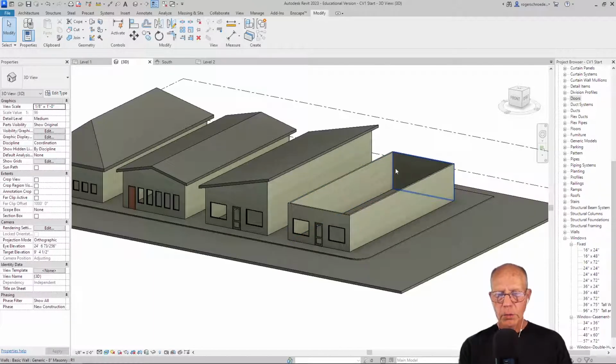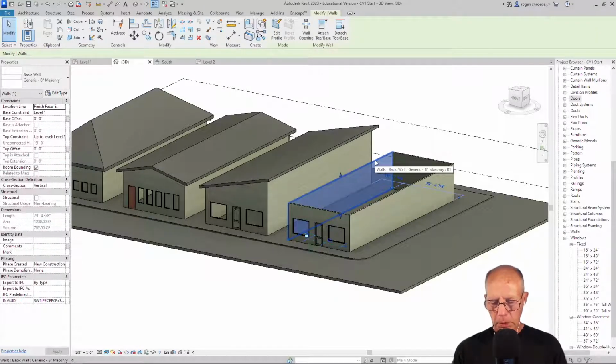We're going to put a flat roof on, and it has what's called a parapet condition, which is something I will cover in lecture if you haven't heard it already. It's the idea that the wall extends up past that level of the flat roof, creating what's called a parapet. So we actually need to make the walls slightly taller than they are. Right now they go up right to level 2. We want them to go a little bit higher.